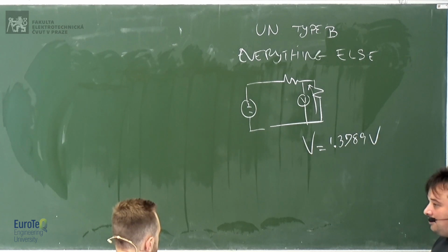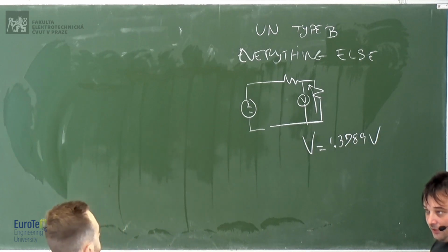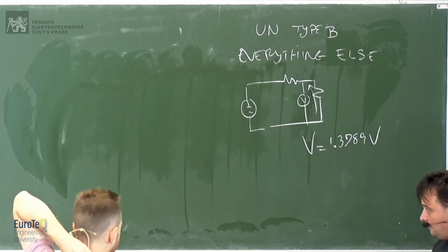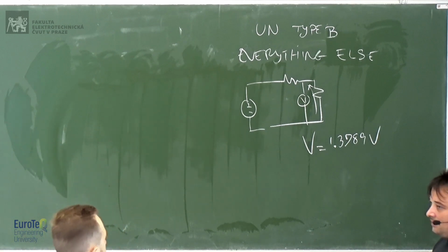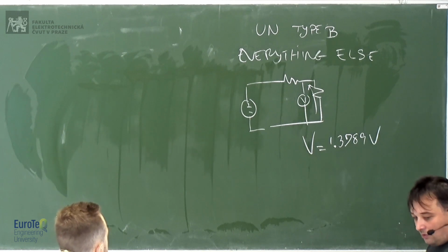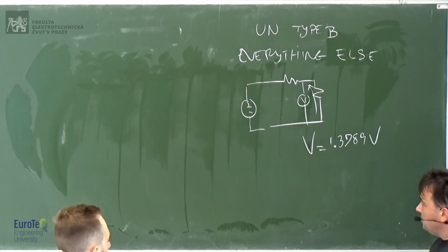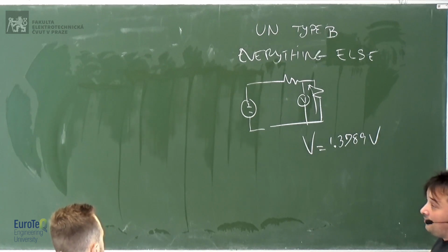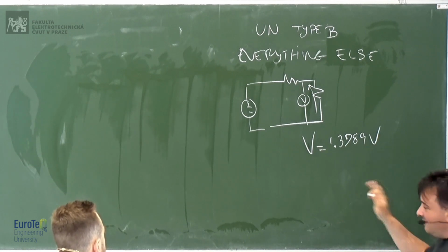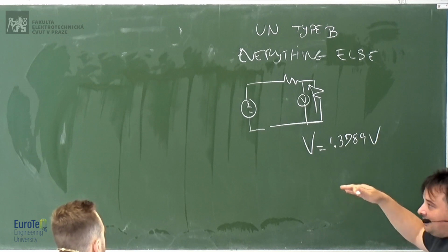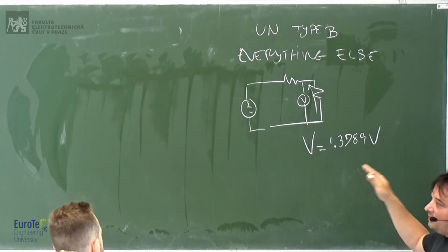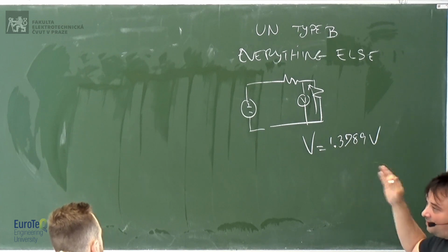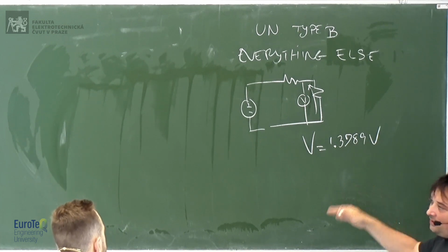If you go to the datasheet of the voltmeter, when they sell you a good voltmeter, of course they make some calibration. If it's something you buy for $5, shipping included, on eBay, definitely they don't make any calibration whatsoever. But a good quality voltmeter needs calibration, and they tell you how long it lasts, because all the voltage references you have inside have some drift in time. They characterize those components, so they know how stable they are in time, with temperature and so forth.